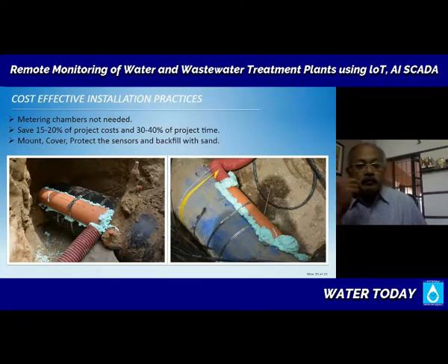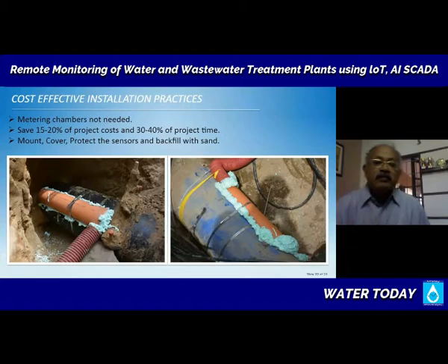Whereas by using the ultrasound technology, we looked at the clamp-on metering. You are able to install the sensor, cover it off, which is what we have done in this particular installation with a part of a conduit, and then fill it up with foam so that the sensors are fully sealed. Remember our discussion earlier that the sensor can be ingress protected to IP68, meaning that even if it is submerged in water, nothing will happen. It will not get damaged. It will continue to operate. So you close it out like this and then backfill the excavation. The pipe is a below-ground pipe, as you see.